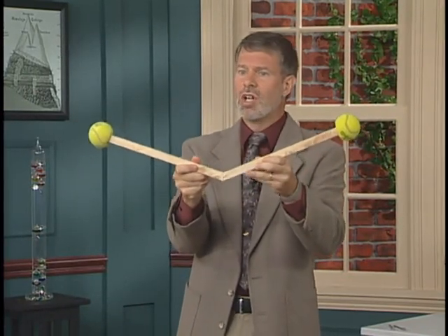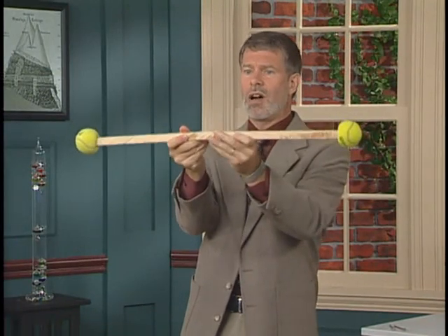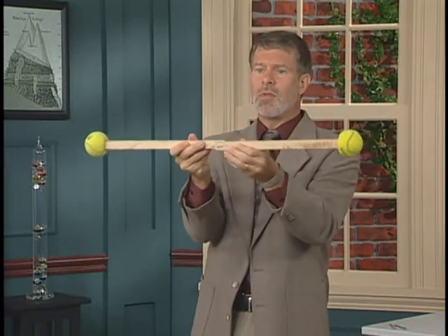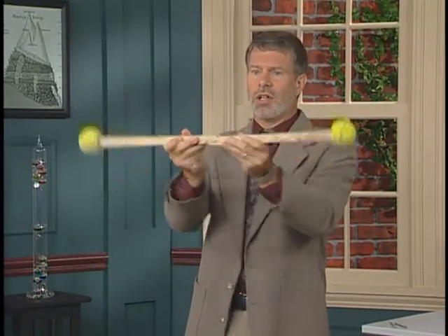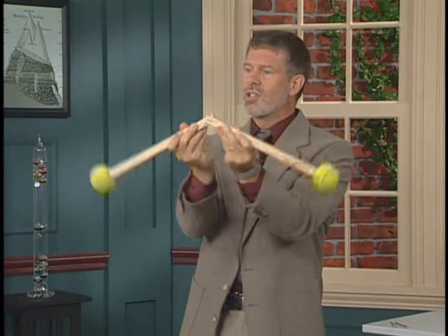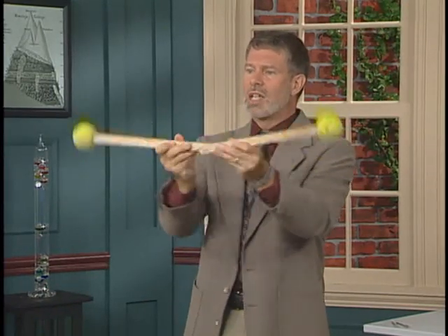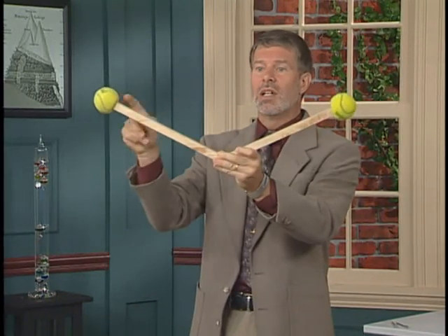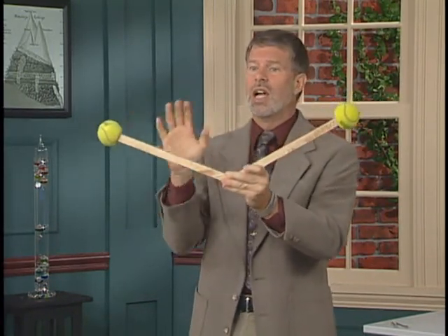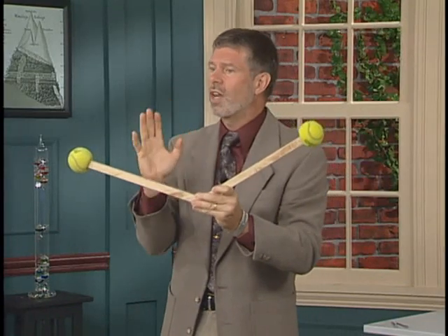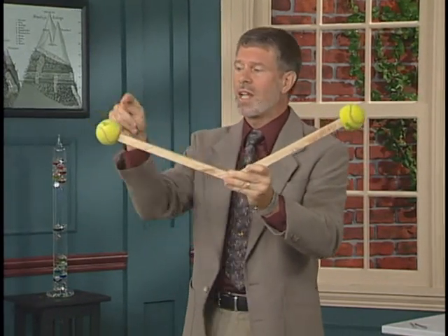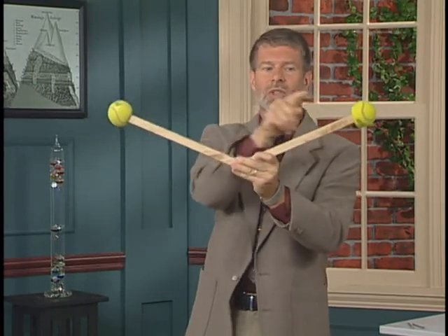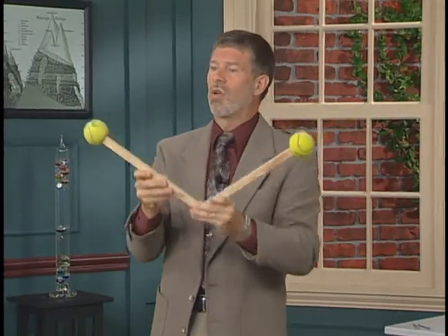Now at low temperature, the two silicon atoms are pretty far apart. And these represent two rigid bonds that have a constant distance. But as the temperature increases, this angle varies more and more as the thermal vibrations increase. And what that means is that on average, the distance between the two silicon atoms is less. They're closer together. And the result is a net thermal contraction. Even though the distances between the bonded atoms, the silicon to the oxygen to the other silicon, those distances don't change, the distance between the two silicon atoms does get smaller.